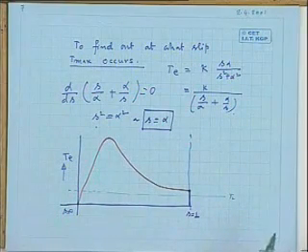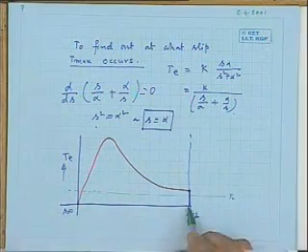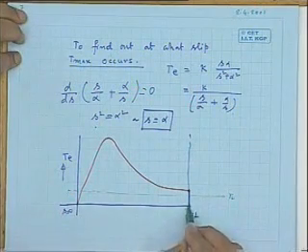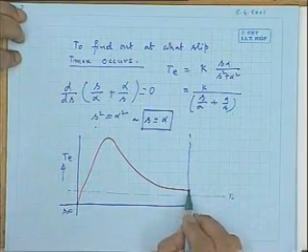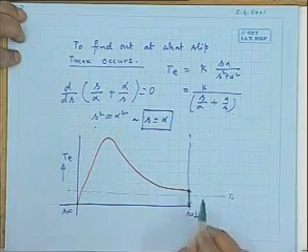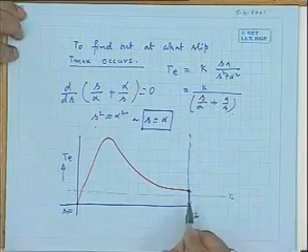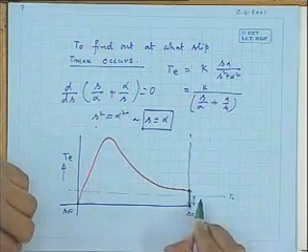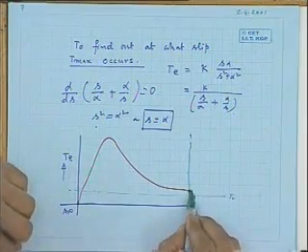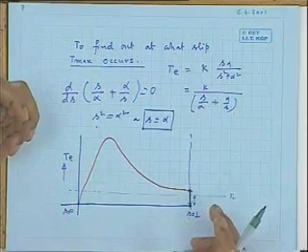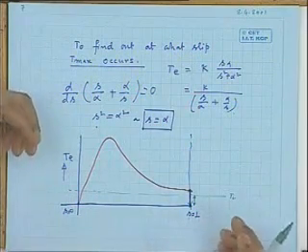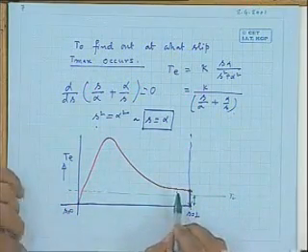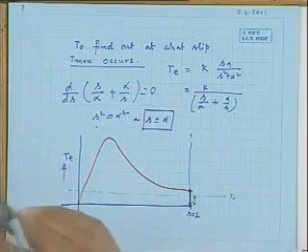It may be, say, frictional torque or whatever it is. Therefore, the machine was in a stationary condition. You have switched on the supply. At that time, S equal to 1, the electromagnetic torque developed by the machine is this much, and the load torque, which is to be overcome by the machine, is this much. Suppose, let us assume, then the difference of these two will accelerate the machine, which will be J d omega by dt, like that. But anyway, the machine will start accelerating.